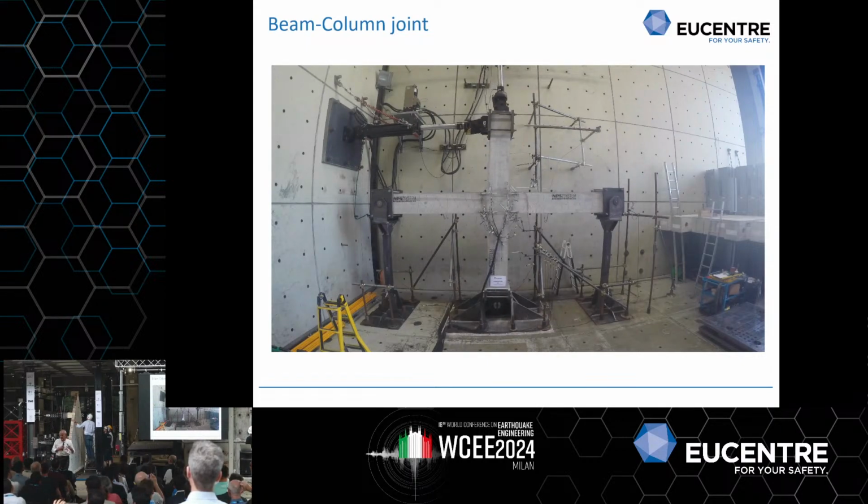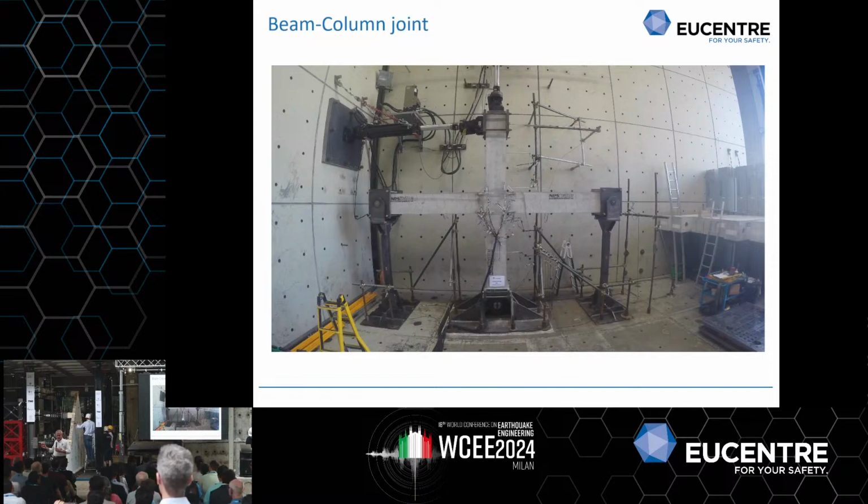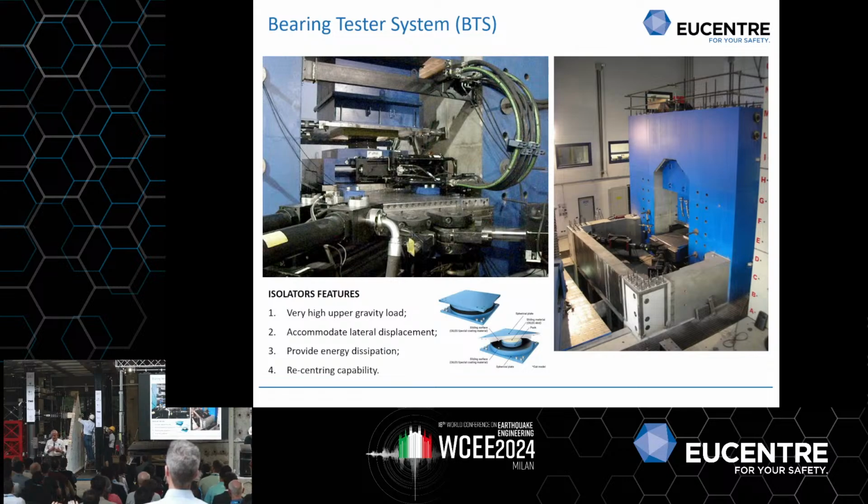The concept is similar in the sense that it is simple. We had at that time a hydraulic system, a pumping capacity, and of course accumulators. Accumulators are used everywhere here because normally we do not need more than, say, 30 seconds of full power capacity. So we use a lot of accumulators that are put under pressure and then can release their capacity of oil flow for a short time.